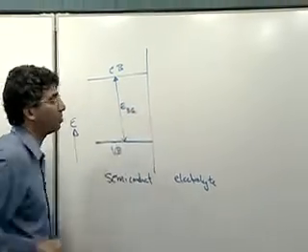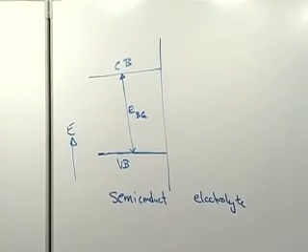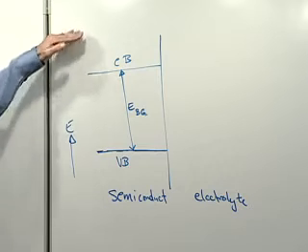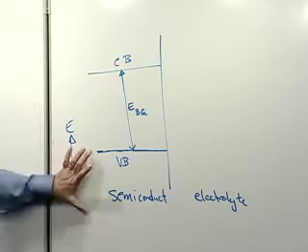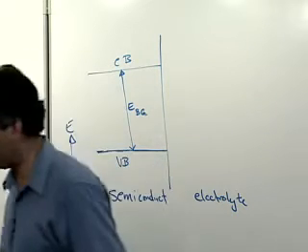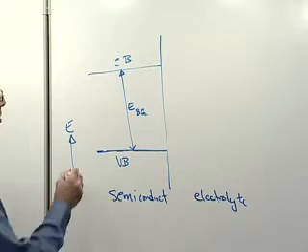And this is what gives your semiconductor its typical color. So silicon is black, right, because it's got a band gap of 1.1 electron volts, which corresponds to absorption of 1100 nanometers. That's in the near IR. It's black. It absorbs all the light greater in energy than the band gap energy, essentially. These bands, in other words, are very thick. There's lots of states in them. Okay, now you know everything you need to know about semiconductor physics. Wasn't that easy? Except for one minor little thing, and that is semiconductors are characterized by something called the Fermi level.